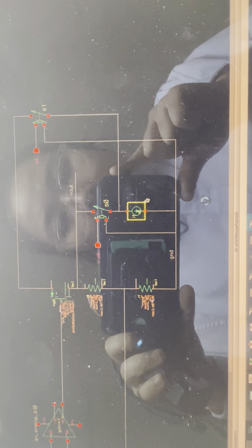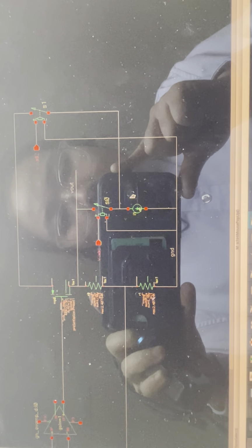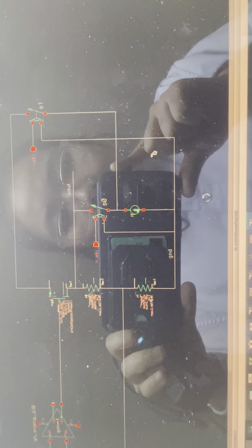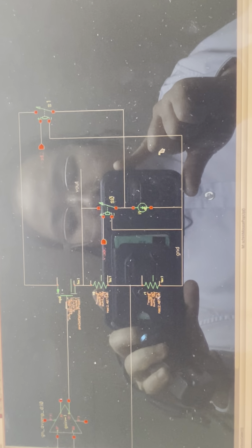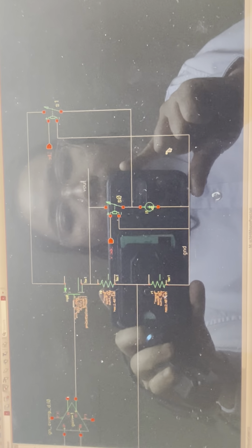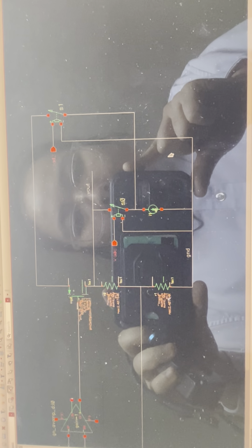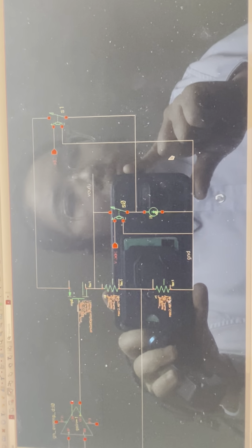Once you have a number for how far you can go, then you should look at stability analysis over the process, voltage, temperature corners, and that will give us an idea of what kind of a current load we can get out of it.